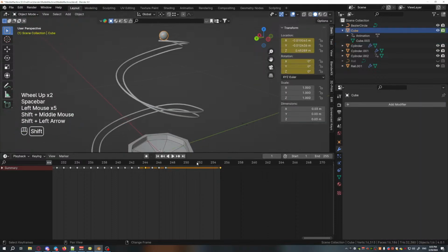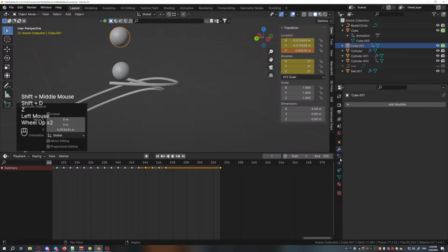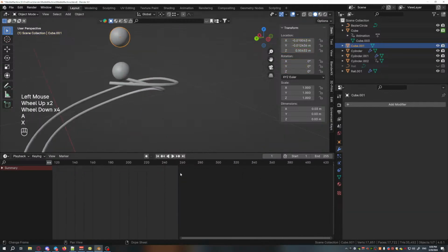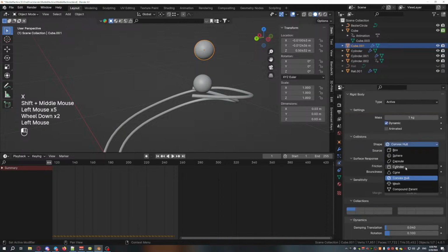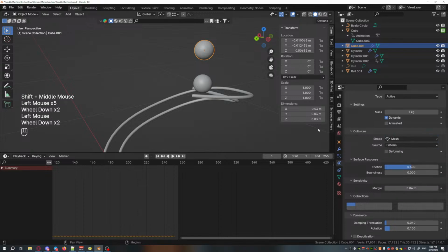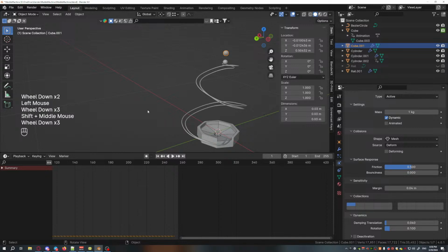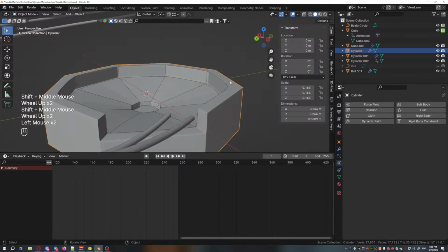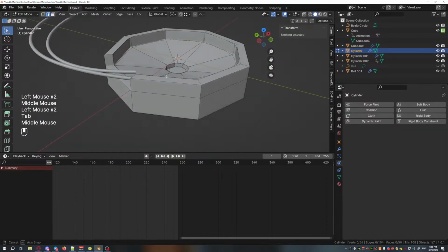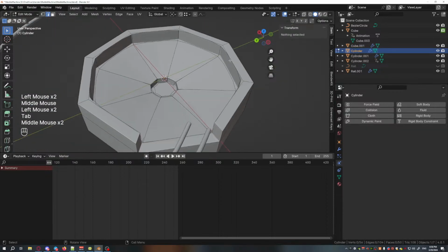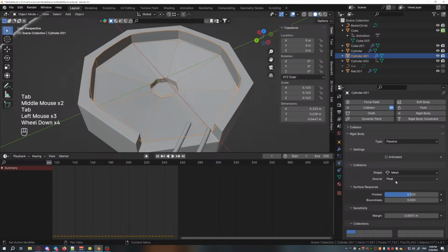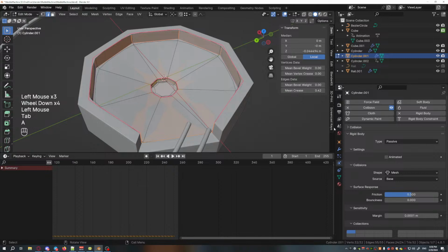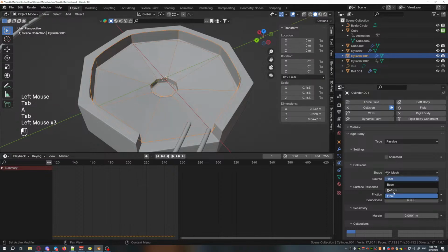When we were making a physical ball there, and when it had no keyframes and just physics, on the rigid body tab, we had our mesh, and no, it is not a ball property yet. It is an object property yet. So yes, we have very simplified basic geometry. But for the physics tab, we can choose what type of mesh we want to use. If we want to use a base mesh, the one that we can see in the edit mode, if we want to use a final mesh, or if we want to use a deform.